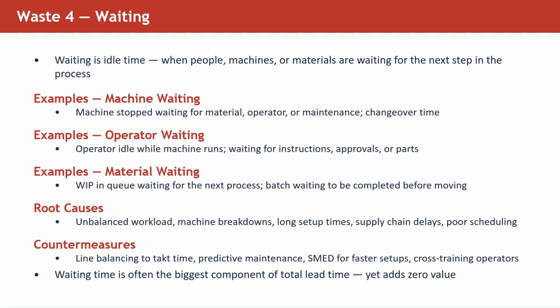Now take any product in your factory and track it from when the order is placed to when it ships. Record the total elapsed time, then record the time the product was actually being worked on. In most factories, the ratio is shocking. A product spends 95% of its time waiting. This is what I said earlier, it's a disastrous waste. If 95% of the time the product is waiting, that means it's killing your time. As we already discussed, takt time is very important when we talk about lean manufacturing, right?